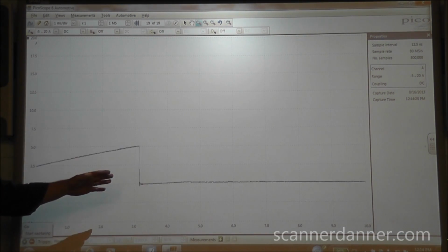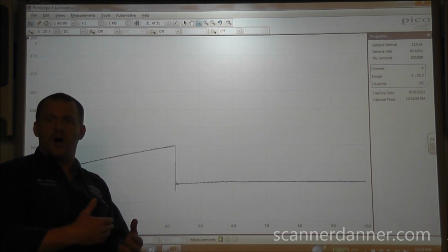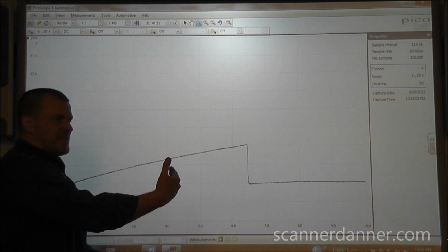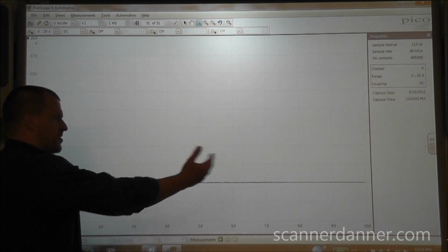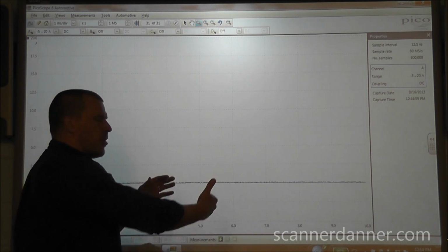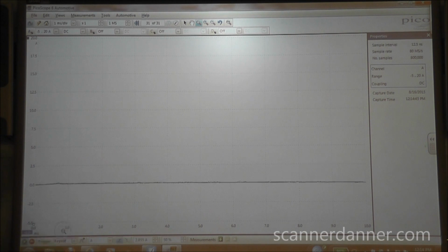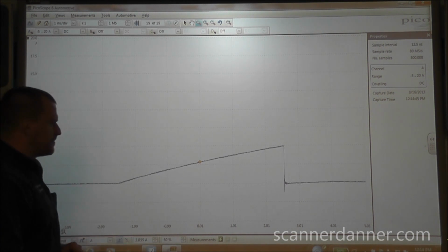So when we want a pattern that's changing, that's on and off, and it's not consistent, and it's coming and going off of the screen, we want to coordinate that firing event with our scope sample. Set a trigger, and that's the answer for that.